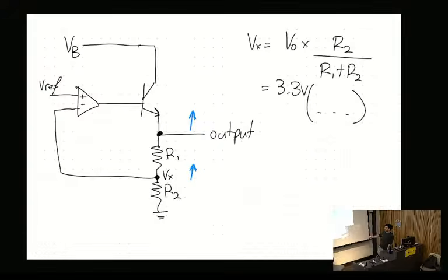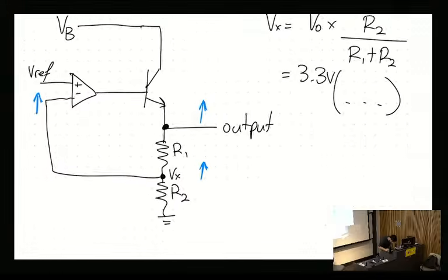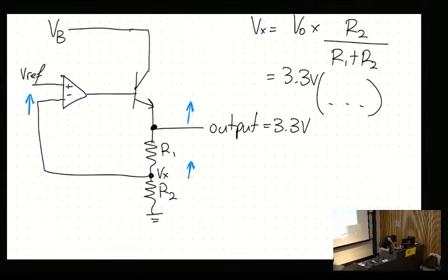That in turn sets our reference voltage. So if that node increases, this node increases as well. And so VREF, if we just say, so this is 3.3 volts. Let's say VREF is half of that, half of 3.3, 1.65. Thank you. I don't know why that was so difficult. Okay. Cool. Yeah, so 1.65 volts.